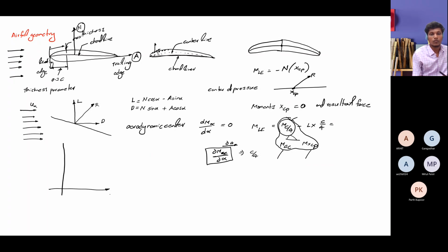And then we should also understand the characteristics of any lift curve of an airfoil, that is CL with respect to alpha, the angle of attack. If it is going from the origin, then we can easily say it is a symmetric aerofoil. If it is not going from the origin and is crossing the x-axis somewhere, then we can say it is a cambered aerofoil. The lift present at zero angle of attack is also important to designate. Sorry, alpha at zero lift.